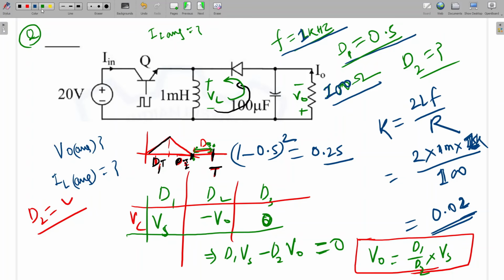So from this circuit, this is the diode current, this is the capacitor current, and this is the load current. Directly from here, we can say that ID average will be equal to I naught average, since the average current through the capacitor is zero. So the average of the diode current will be equal to the average of the output current. Is it clear?